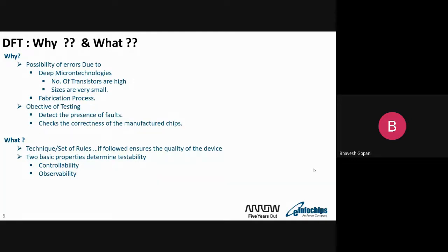Sometimes the error may be due to the pattern, or sometimes it is a real defect. So this is a very crucial step when we are doing debugging in post silicon. Once silicon bring up happens, we need to identify those manufacturing defects, and prove whether it's a real issue or only a pattern failure or vector failure, where the vector is not as expected.